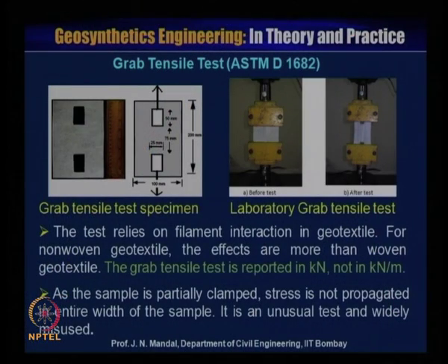Next, we will talk about the grab tensile strength as per ASTM D1682. In this test, you can see the sample like this, where the size is about 50 millimeter, in between is 75 millimeter, then again 25 millimeter, and this will be the clamp, this will be the clamp, and this is 100 millimeter and this is 200 millimeter, and then you have to clamp here like this.